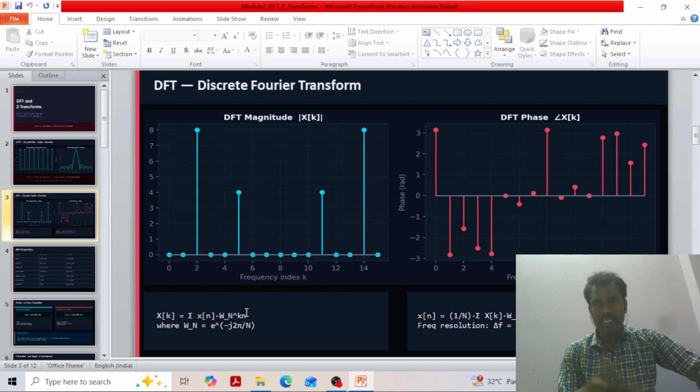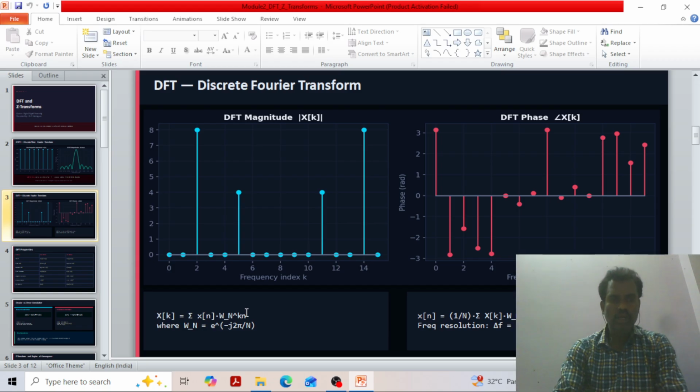and it needs addition of 4 terms to calculate one multiplication again. So it needs more calculations if the signal becomes complex. For higher values of N, the complexity rises. So it will not be efficient for performing Fourier transform for real-time signals, because the N value is very high and it needs more computations.